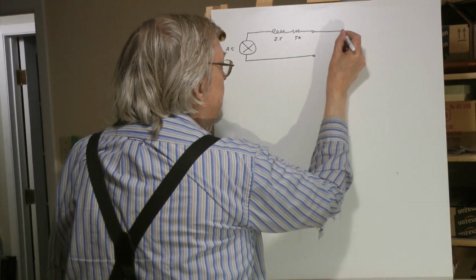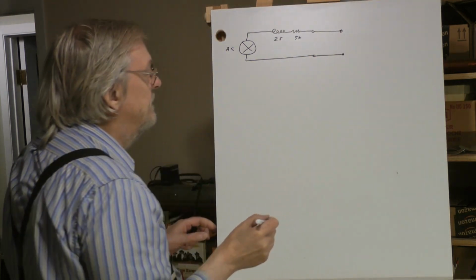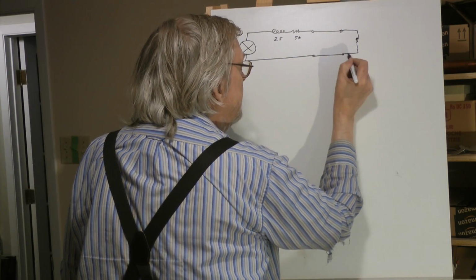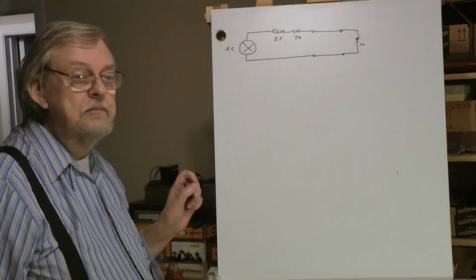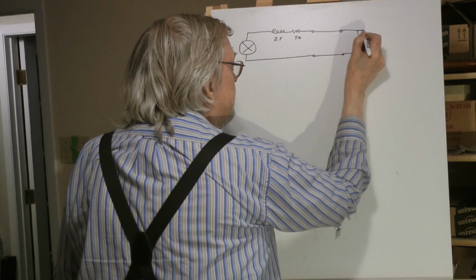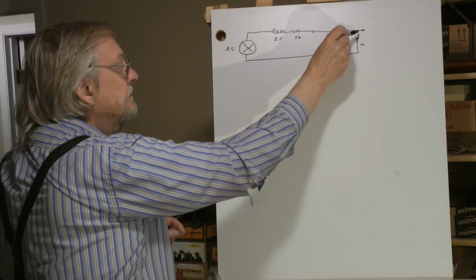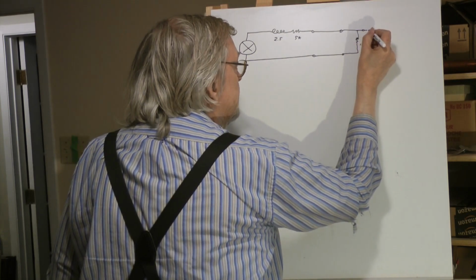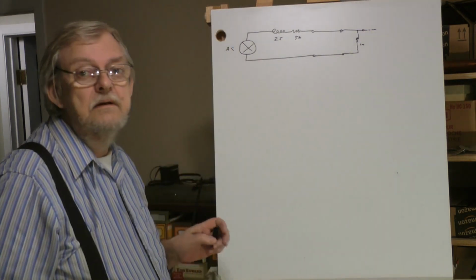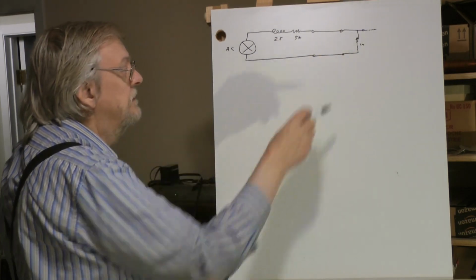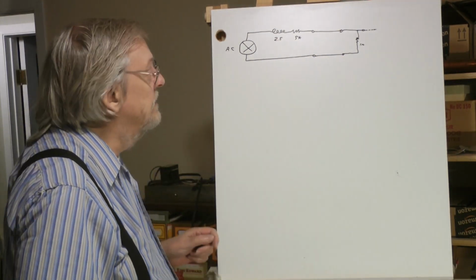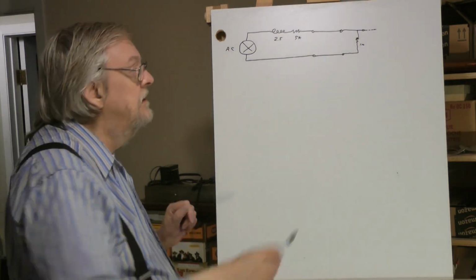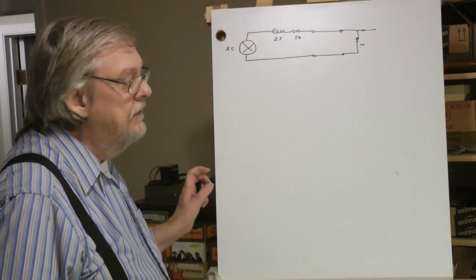Next we have the cable. We'll look at that in a bit. The amplifier, it's a 1 meg ohm load usually. I'm talking about a vacuum tube amp. This is the point we're interested in. That's the voltage that we're going to amplify to listen to. It typically goes into the grid of a tube, but there's no grid current. So since there's no grid current, there's no voltage, there's no nothing. It more or less doesn't exist. It just takes the electrostatic field, you might say, modulates the electron beam and blah blah blah.